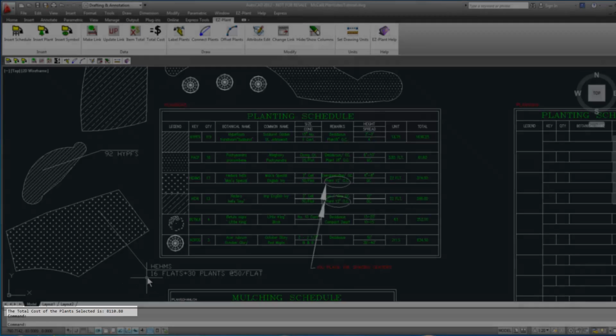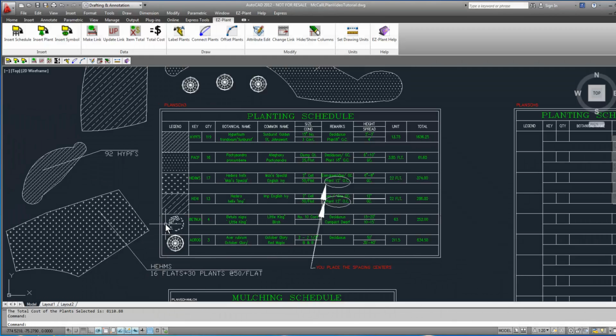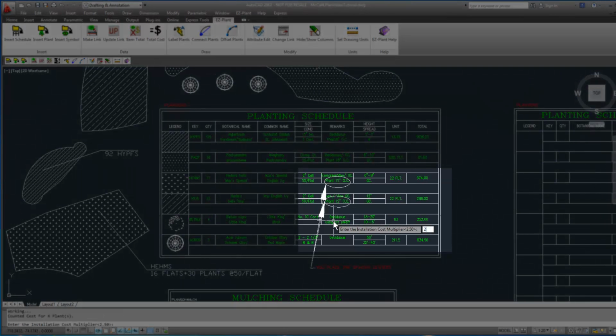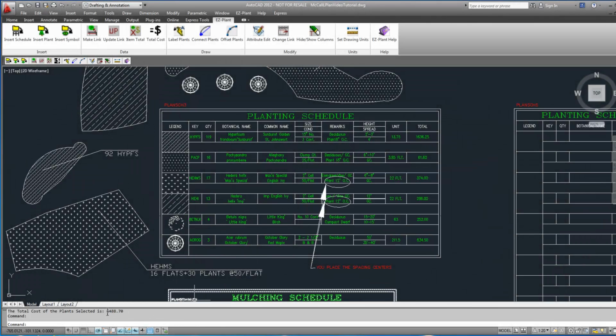Now, personally, after preparing hundreds of landscape plans and using this software for almost 20 years, I've found that more times than not, using the installation factor is very close to the actual installed contractor's cost. I have found that I bump up the installation multiplier if there are many shrubs or ground covers in a project, or if it requires a lot of handwork, or if the work is in a metropolitan area. In a rural area I use a 2.0 multiplier, where budgets might be less than in a city. In a city I may use as high as 4.0, so it's the user's choice.